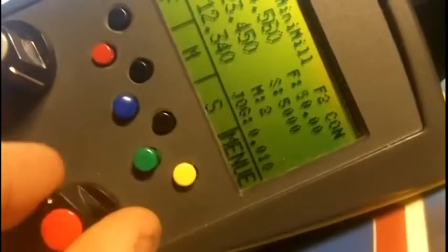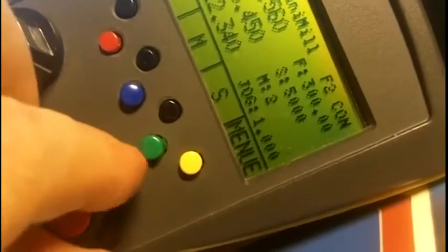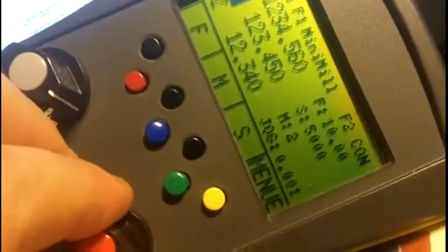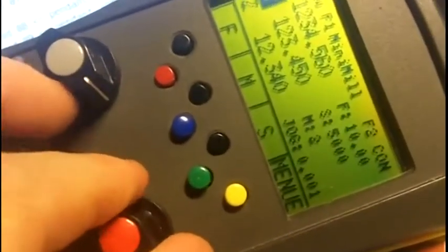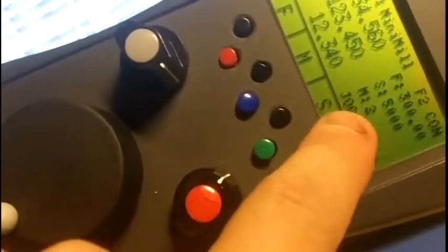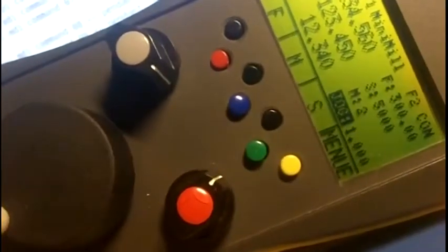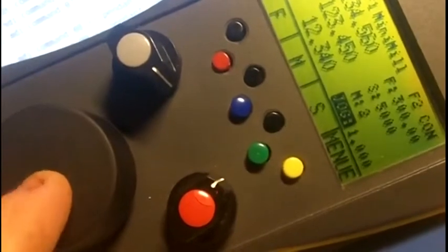X, set here. This selects the increment. As you see down here, the increment is selected. Let's go for 1 millimeter. The chuck button here, the MPG wheel, also has a switch. If I press, you will see here it's on and off, on and off.